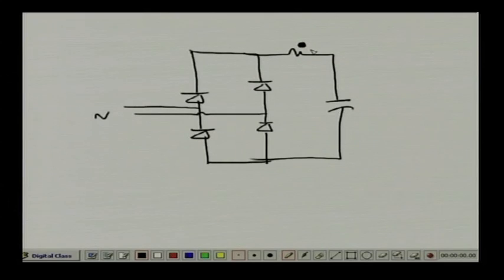So what will happen to this resistance? Its value decreases, which is what I want, because it is a loss of power that will never be utilized. The efficiency of your power supply will deteriorate just to protect 4 diodes.